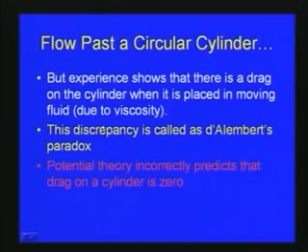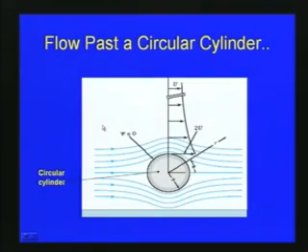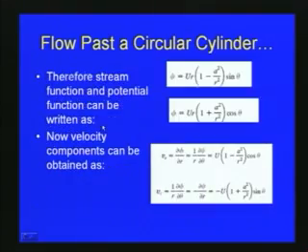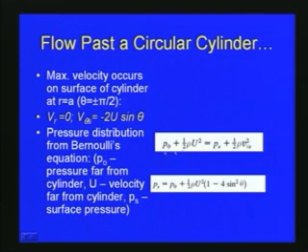With respect to the previous figure, we can apply Bernoulli's equation here. So, we can write P 0 plus half rho u square is equal to P s plus half rho V theta s square, where V theta is already defined here. P 0 is the pressure far from the cylinder, that means much beyond the position of the cylinder, and u is the velocity far from the cylinder, which is the uniform flow velocity, and P s is the surface pressure.